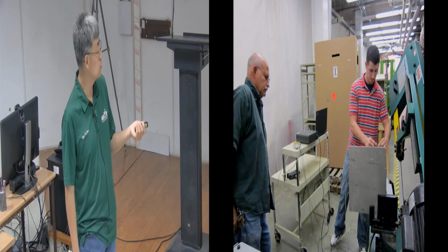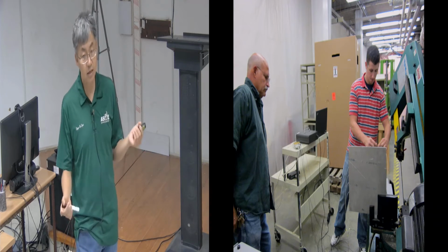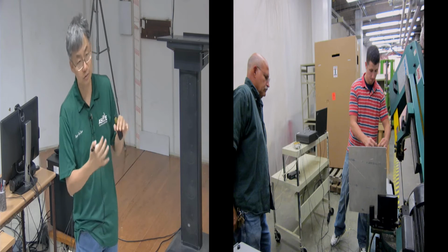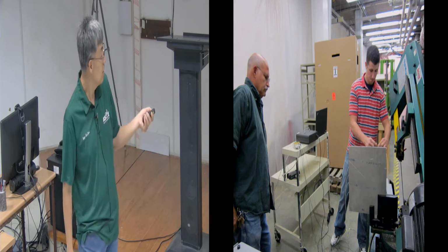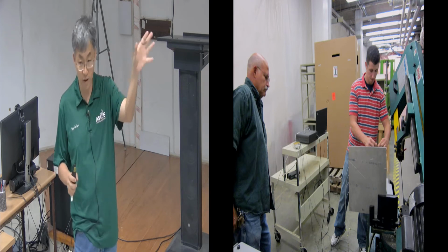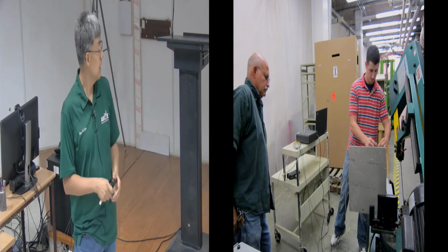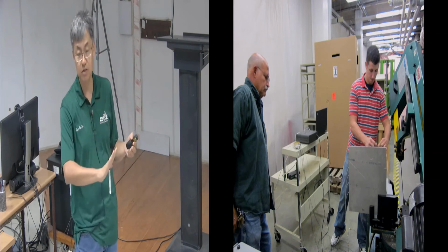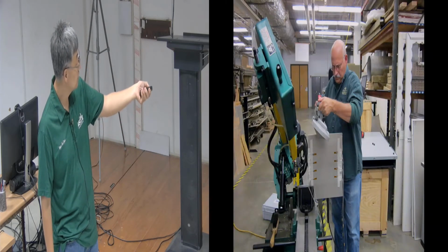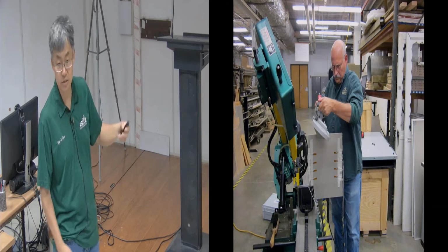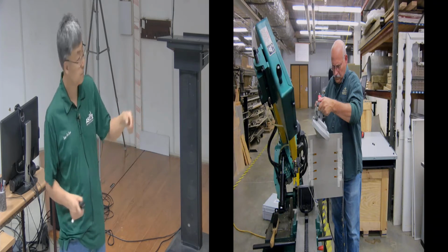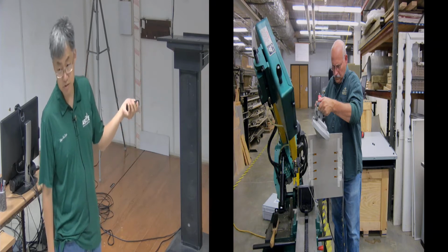Trying to address that issue, we did a very small experiment in the lab. Luckily, from measurement science, I think there is a way to converge the two. It's just how to do it; I'm not understanding that part yet. But we basically use a piezoelectric sensor system that can create a guided wave technique on that plate, and at the same time we measure the external surface deformation using LiDAR. We clamp the plate on the corner and put these piezoelectric sensors on it. The piezoelectric sensors generate high-frequency acoustic waves, like ultrasound. This is a system developed by Stanford University.